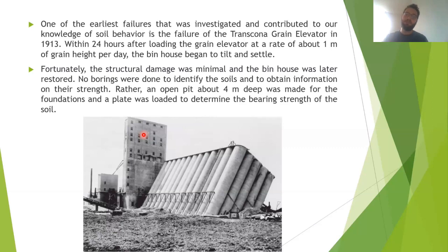In general, the rule for construction is that 1/370 of the height of the building you can have a tilted top. So for the Burj Khalifa, the top can move 5 meters left and right, normally. Nothing is going to happen. If the top moves 5 meters, that's still okay because of the elastic properties of the construction.